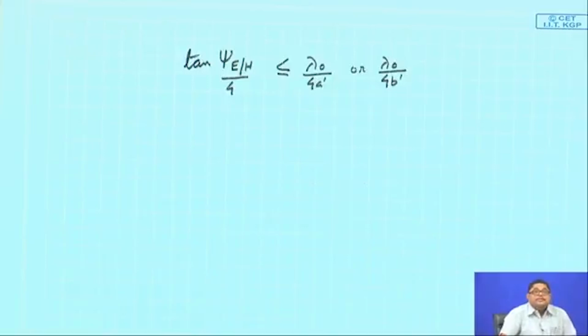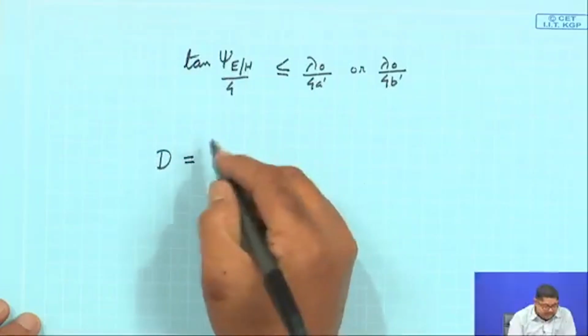So, for a fixed length horn, if I am allowed to do maximum gain thing, then people do that. For H plane, they suffer that 0.75 pi phase error, and in the E plane suffer that. So, for that, what will be the gain of a pyramidal horn?